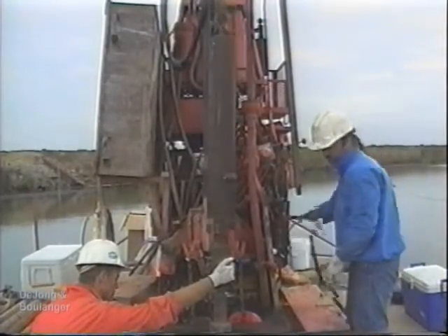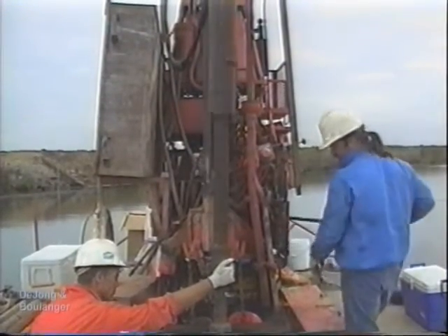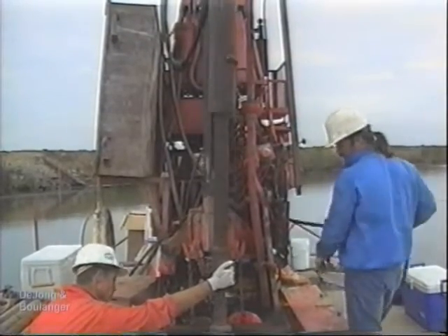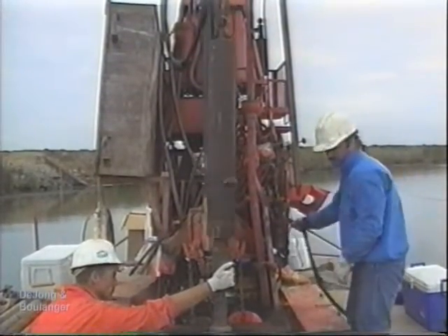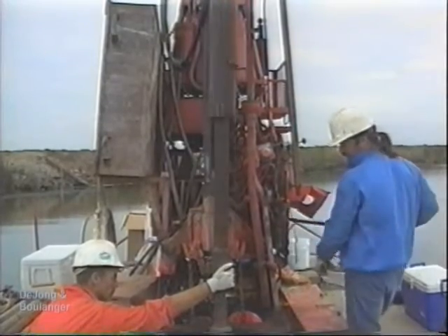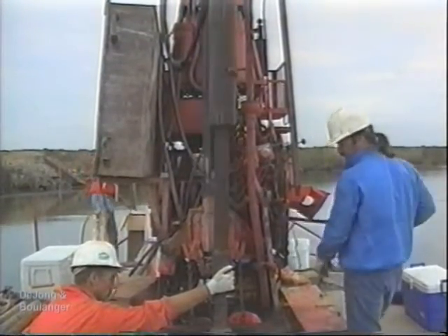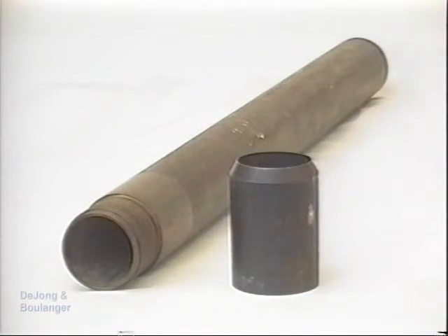When mud rotary drilling in cohesionless or highly erodible soils, an outer casing is used to create a closed circulation system. Casing is advanced concurrently with drilling until it is seated in dense, unerodible soil or rock, creating a closed circulation system. A shoe, made of hardened steel, is attached to the bottom of the lead casing to prevent the casing from buckling while it is driven into the soil by the hammer.